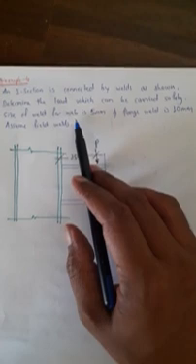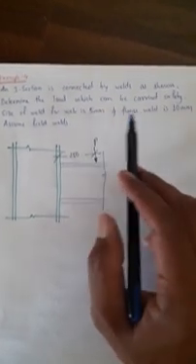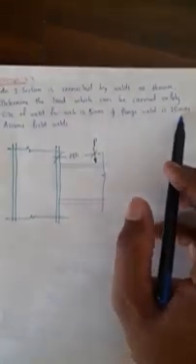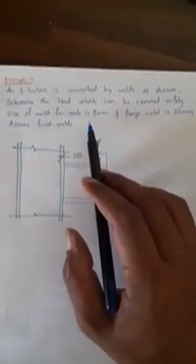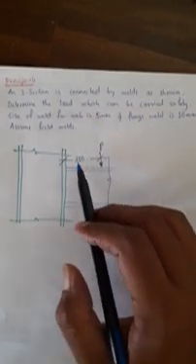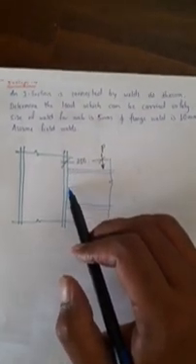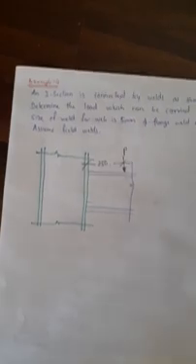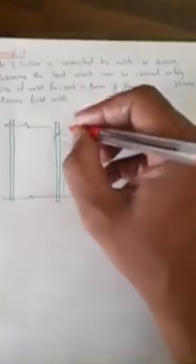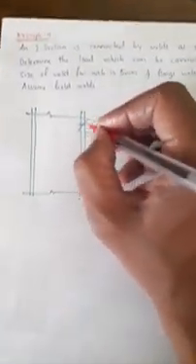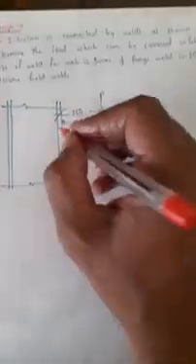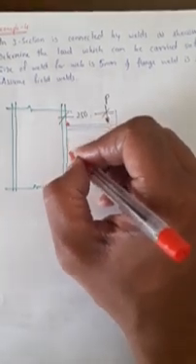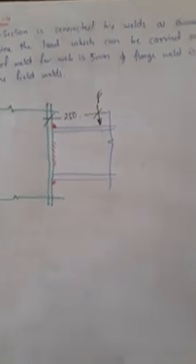The size of the weld for web is 5 mm and flange is 10 mm. Assume field welds. So note down the things here. Size of the weld for flange and for web, they are different. Now let us mark those welds. Let this be flange weld, this is the web.